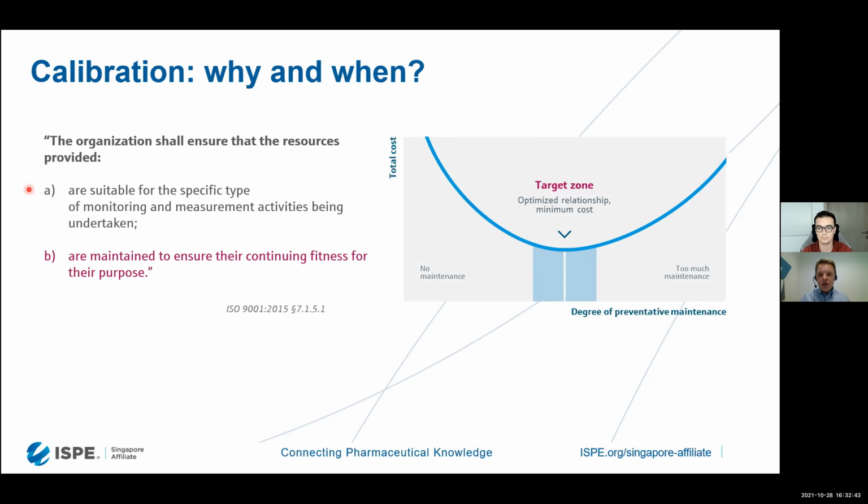And actually, none of the worldwide regulations, like ISO or FDA, stipulate that the intervals have to be fixed forever. On the contrary, it is recommended to periodically review them. Some of our customers have them reviewed on a regular basis. Some of them are dynamically reviewed, meaning that it is not only the result of the past calibration that affects the further interval. It's the result of all the history of the devices, not only the metrological history, but also the properties of the devices, which affect the calibration interval.